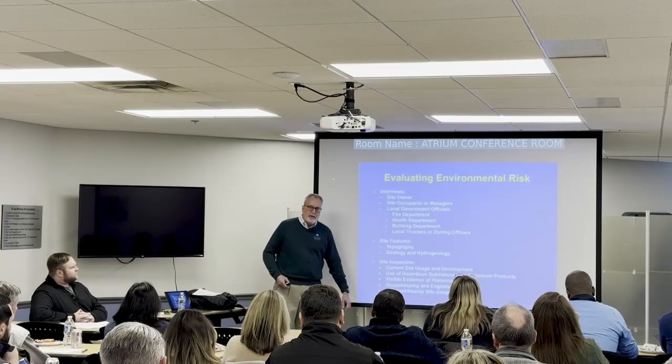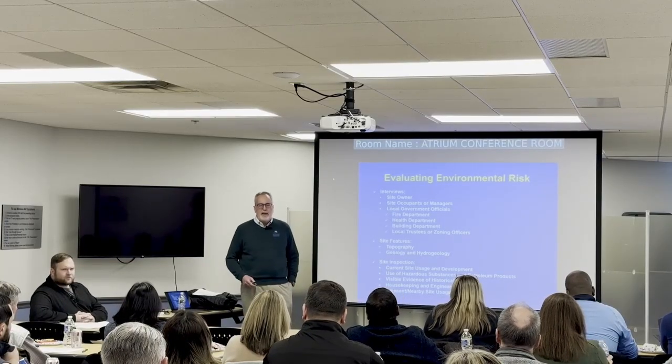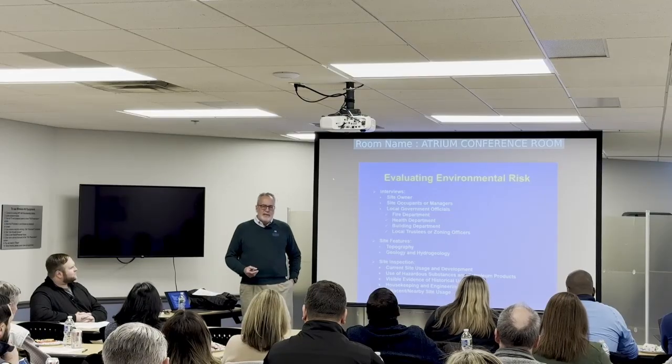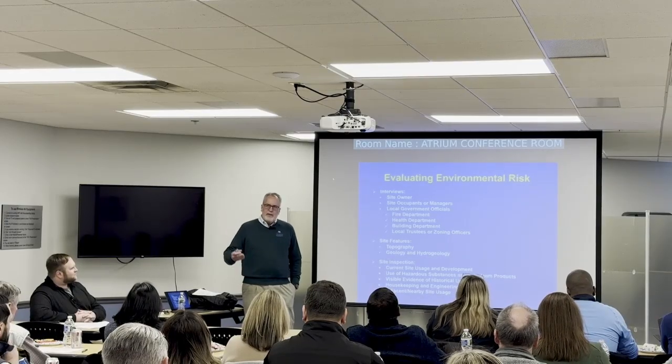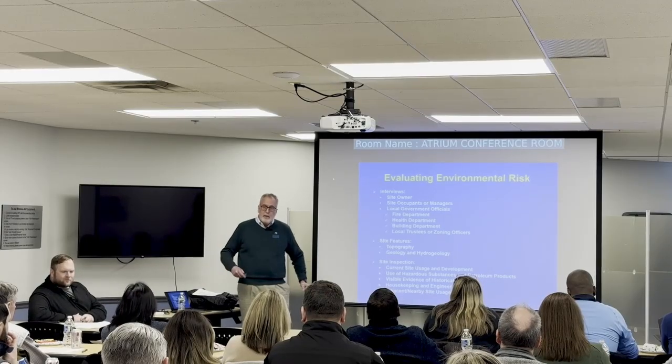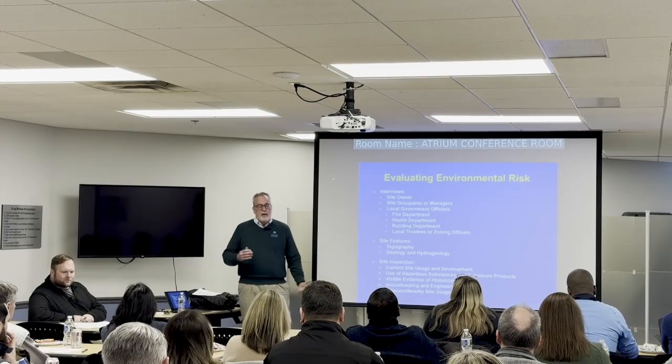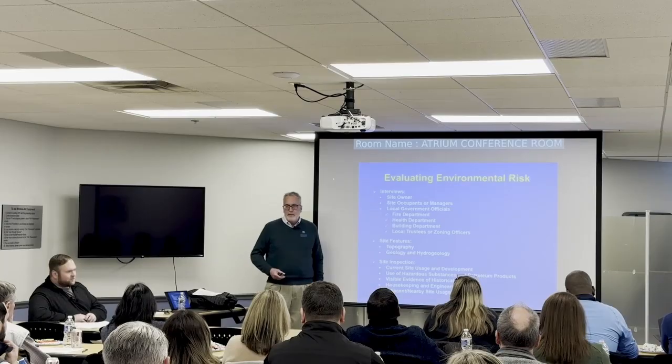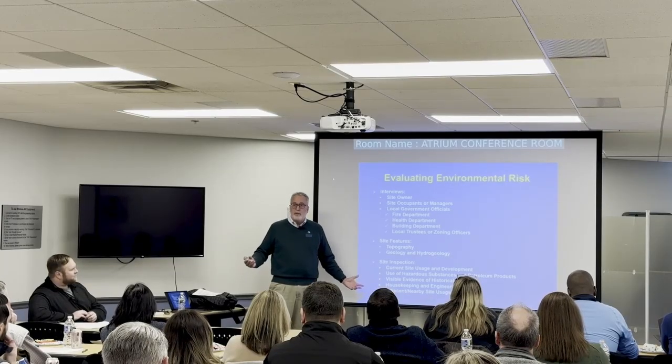We just looked at a site a couple weeks ago. A client was going to buy a gas station in a small town, and I looked at it and thought, this looks like sand and gravel, and it was all sand and gravel. Sure enough, 3 doors down there were probably wells 40 feet deep, straddling the upper saturated zone, and it was a 50-year-old gas station. And I'm like, there's a lot of risk here.